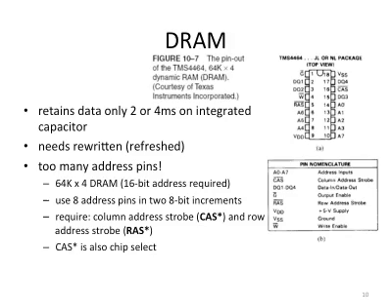So in total, to access these 64K locations, you need 16 pins. Now, this math is simple, but adding more pins to a chip turns out not that simple. There are many challenges in terms of packaging, and how you route the signals out of the silicon area to the outside. And when you have higher capacity, let's say 1 meg locations, that's 20 pins required. So this number can go up very easily.